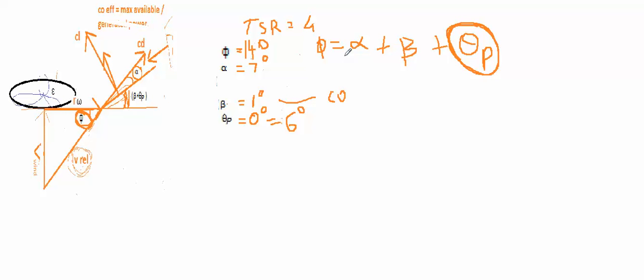As the angle of inclination phi changes, we want alpha to be constant. Beta, the twist angle, is designed for a particular tip speed ratio, say for example 8. But as the tip speed ratio changes, this angle of inclination changes.